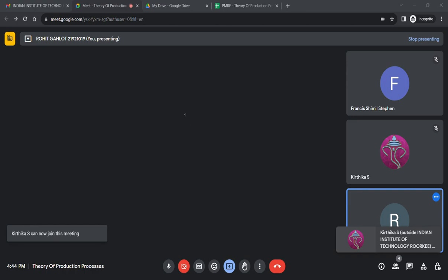Firstly, suppose this is your casting which needs to be filled. Your entrance is this way, from the pouring basin and all, and this is being filled with your molten metal. So firstly this is your bar, because its width is less than 3 to 4 times its thickness. If that is the case, then it will be called a bar feeding plate. But if it is another case, where the filling is done from the opposite side, then it will be your plate feeding your bar.